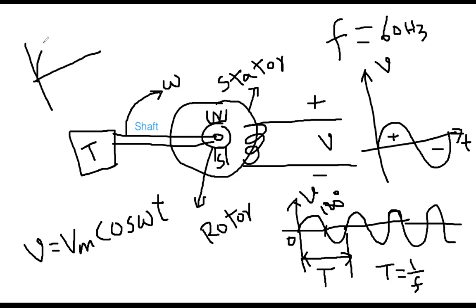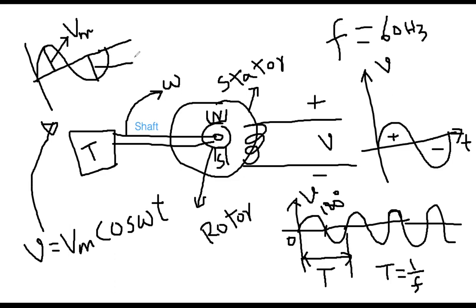Now here I am drawing one more thing. Once again, just look at this one cycle. So for example, this is the waveform of this signal, that V. So what is the Vm? Vm is this portion. From here to here, this amount is called the Vm. Or from this point to this point, this is the negative side, this is minus Vm. So therefore, when I am writing the Vm, this is called the peak. This amount is called the peak or the amplitude of the waveform.